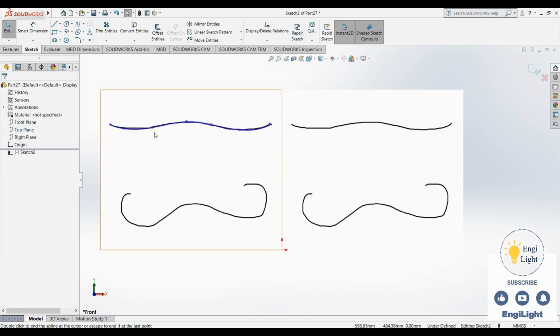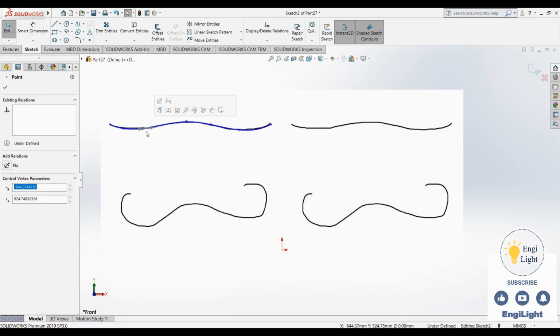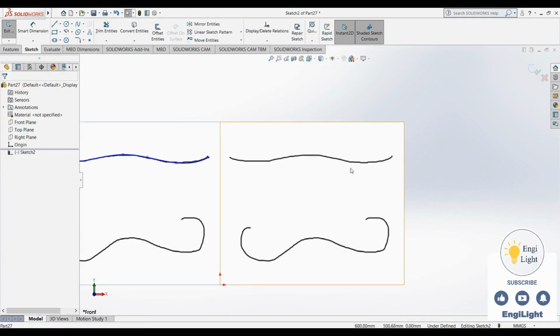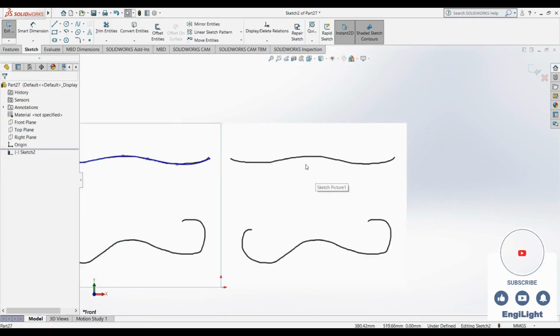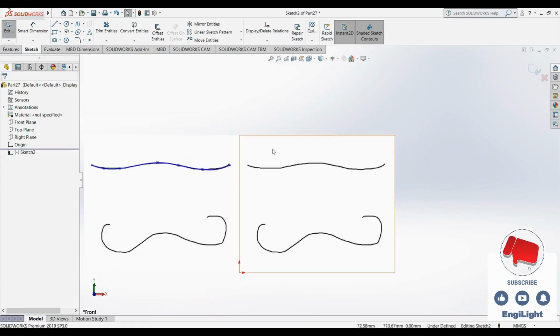This way, I'm tracing the curve so it perfectly matches the line in the reference image I prepared earlier. Okay, now let's draw the same line again using the Style Spline tool. I see 3 distinct curves, this one, and this one. 3 inflection points mean we need a degree 4 Bezier. That requires 5 control points.